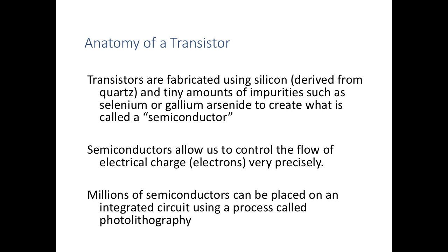And the silicon is often created in an extraordinarily pure form known as a silicon ingot. And this is then sliced using a wafer slicing machine into something that can be imaged with multiple chips onto a single dinner plate sized wafer. The wafer is then sliced and diced and mounted onto a die that effectively allows us to wire contacts to an external point, typically a pin or a ball in a grid array, and these are then used to make our connections.